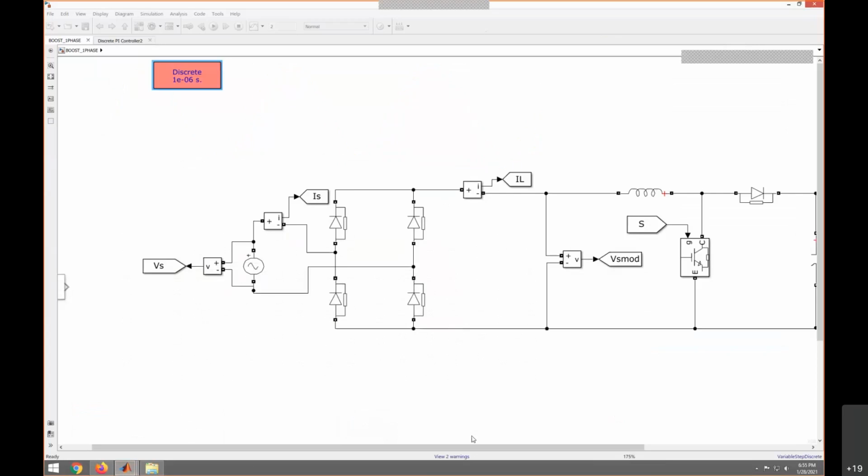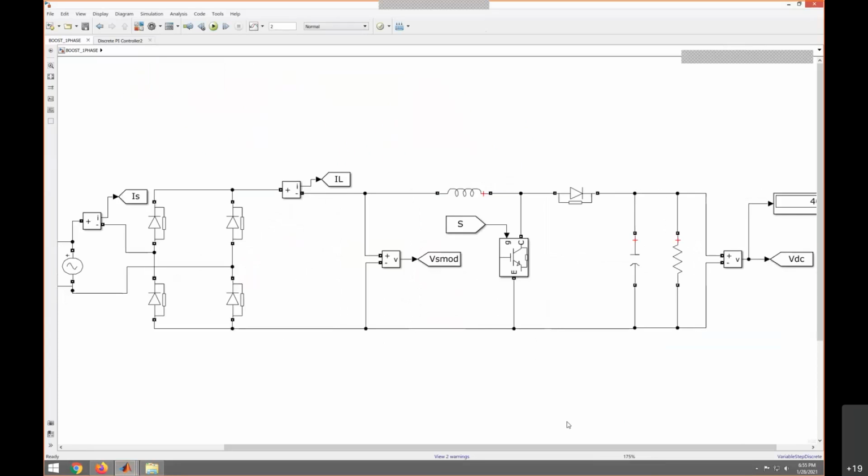We already discussed in previous classes how to tune this inductor value. If you increase the inductor value, the current switching ripples will be reduced. If you increase it to a higher value, what will happen? The waveform tries to bend to the other side. So that is the point where you need to understand that the inductor value is too high.